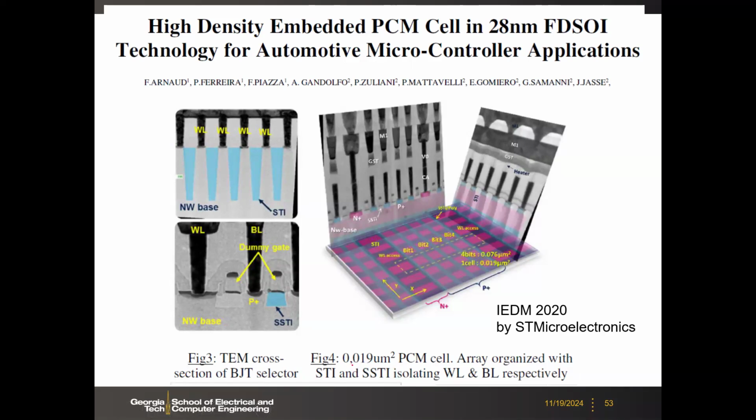You know this number. Do you see this number familiar to you? This is the same as 3 nanometer SRAM from TSMC, the cell size, the same size. But this is a 28 nanometer platform, 1T1R. But that T is BJT. Okay. So this could be attractive, right? So you get the density of 3 nanometer SRAM, but in this 28 nanometer platform, right?